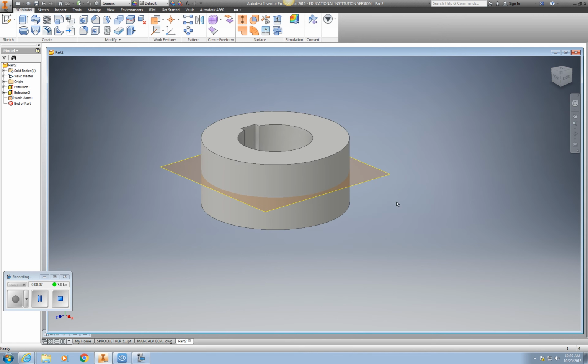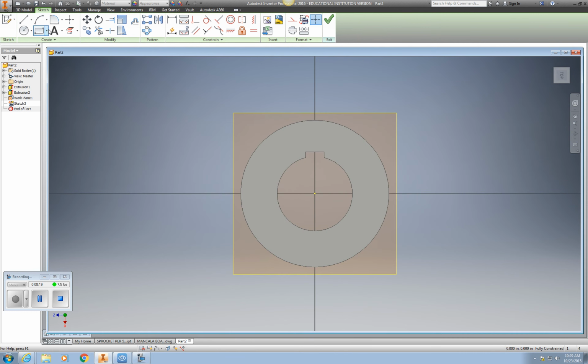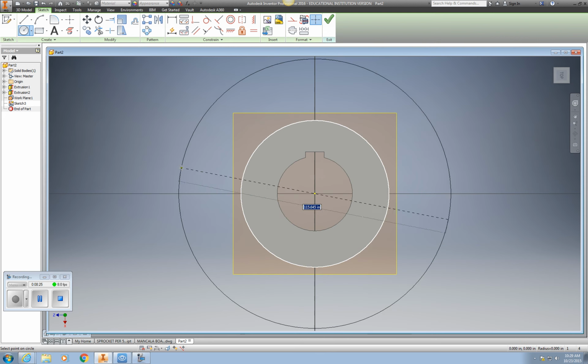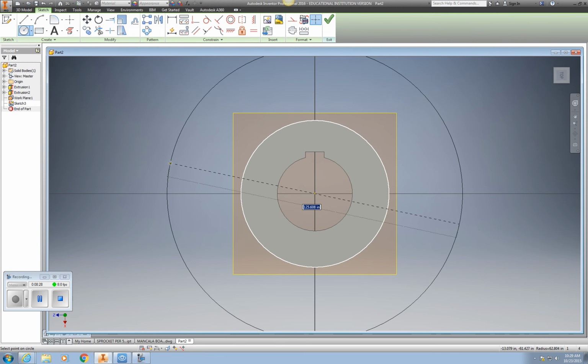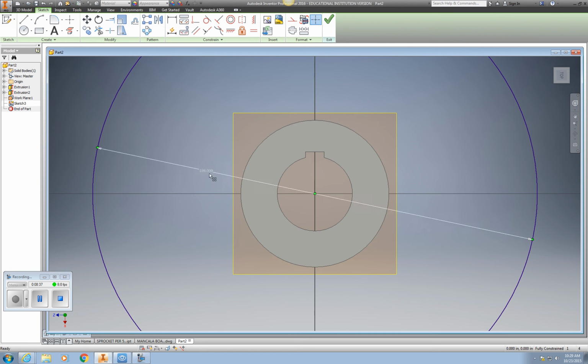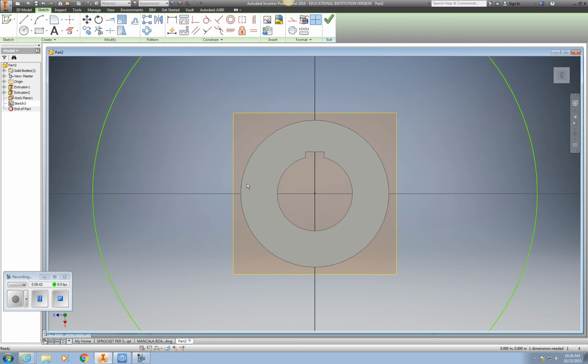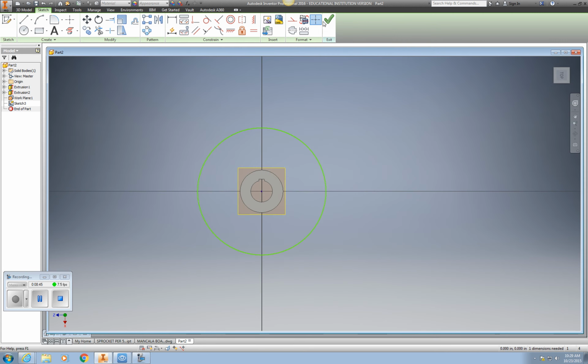So now by clicking on this particular surface, I can now create a sketch, and I'm working off the center. So my large circle now, I'm going to look at my right side section view, and at 189 is the outside. So let's go ahead and put the 189 in. And let's go ahead and delete the dimension.